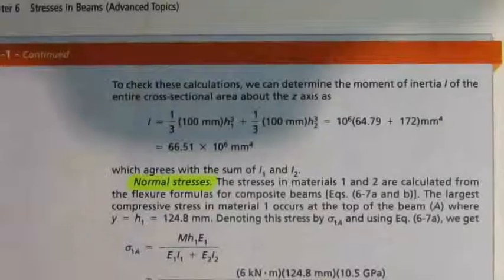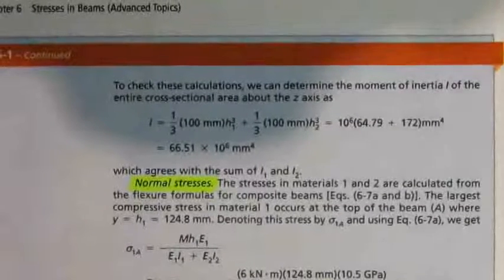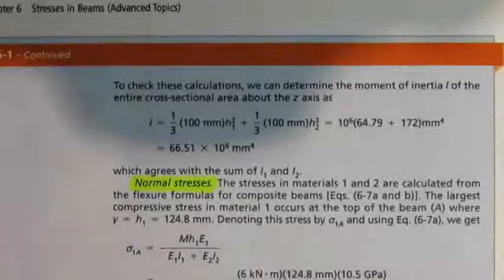Just to explain what I mean when I say local neutral axis, let me quickly draw here. Let's say this is our problem. This is how it looks, and this is the steel part, and that's your wood. This is the local neutral axis. If this part of the wood is 150 long, we know for sure that the local neutral axis is definitely here at the middle, at 75, which is halfway.